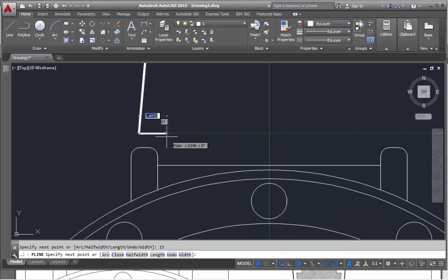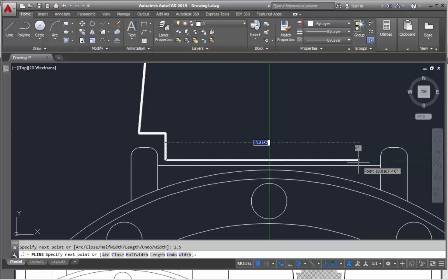Now we're going in 1.5, so make sure it's horizontal. 1.5, enter. I hit the comma there by mistake, so to get back, again, use the tab key and 1.5, and then I need to go comma 0 this time. That's going to go 1.5 mil in that direction. Then make sure I'm vertically down. 1.5, enter. I think it was 11.5 going this way. Enter. Then coming back up.